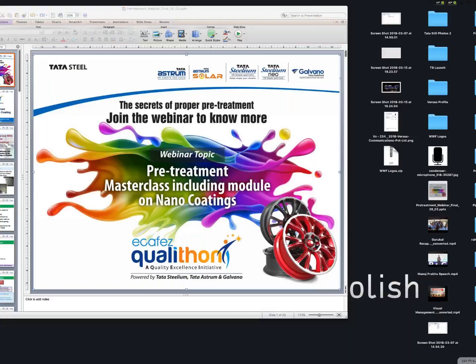Mr. Bishwajit Thakuria asks, how frequently do we need to replace RO water for degreasing, phosphating and passivation tanks? You mean how frequently you have to discard these tanks or replace RO water? I did not get your question very correctly. But for degreasing tanks, phosphating or passivation, usually your chemical suppliers will give you the discard frequency and you have to stick to that.